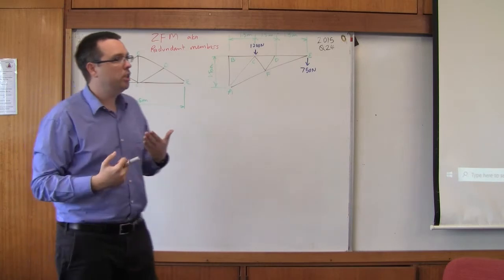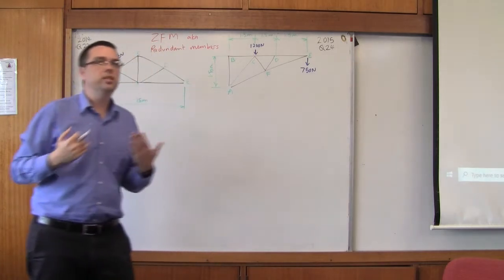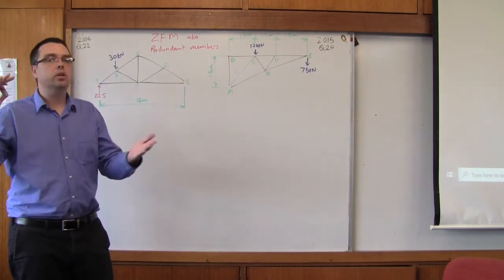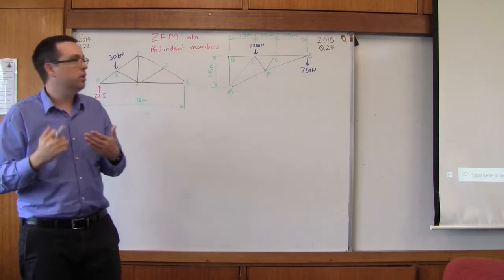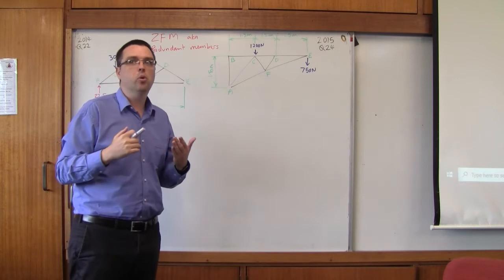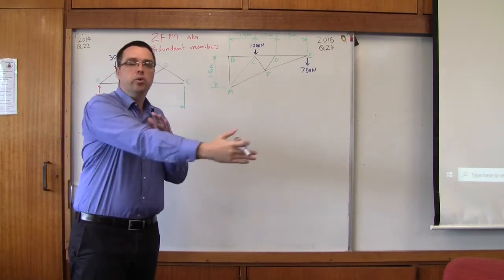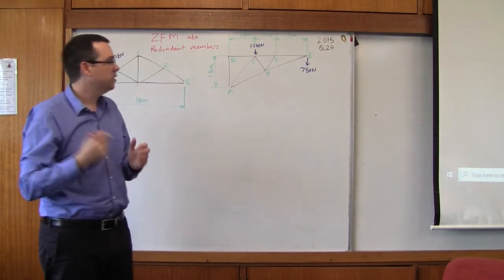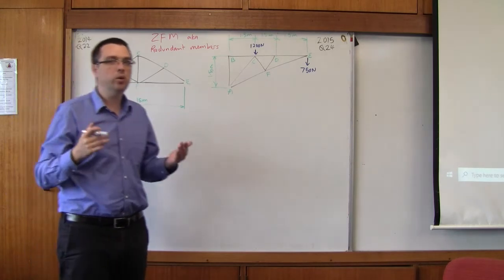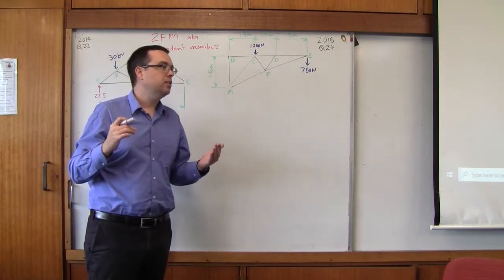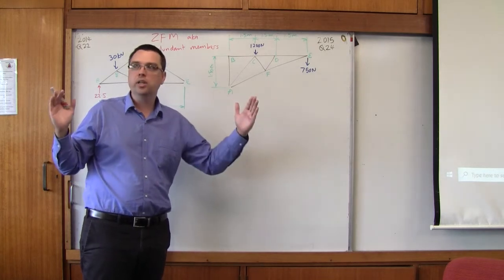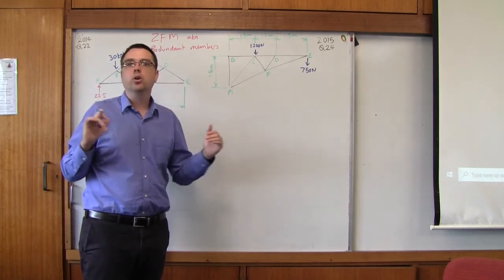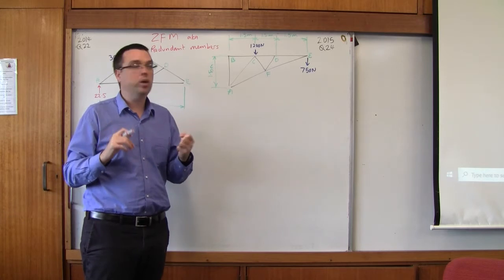Another explanation is that redundant members can be important for bracing, so that we don't have long lengths. We can have something to reduce the effective length of members, and that can be useful for bending. The longer the distance between supports, the more the bending stresses increase, and compression is also affected by longer length: the more likely it is to buckle. So that's where we can have bracing.